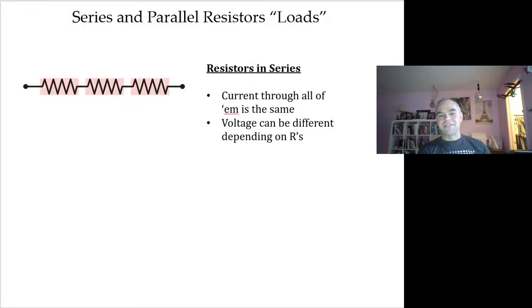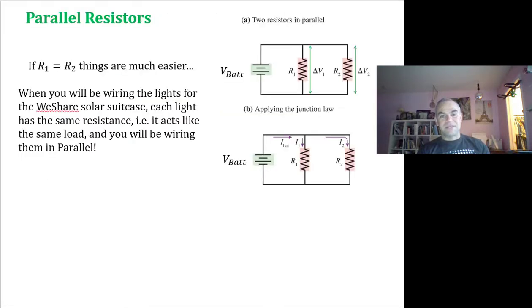This is an introduction. But you can see that in this case, if all these resistors are in series and I pulled one of these resistors out, then I'm breaking the path that the current can take, and current won't flow through any of them. But if they're in parallel, like in this case here, if I pull this resistor out of the circuit, there'd be a big blank space here. The current would just all go to the other resistor.